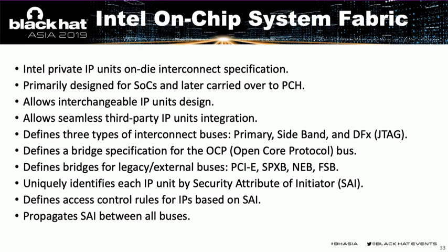We have found that the IOSF specification defines 3 types of buses: primary, sideband, and fabric. Also, the IOSF specification defines a bridge to the open core protocol bus with open specification. Also, it defines a number of bridges for legacy and external buses. For example, when a PCI Express device issues some transaction, it goes a long way through IOSF segments and IOSF bridges, and finally arrives at the system agent and memory controller.